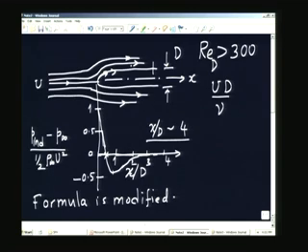If there is friction, there will be some pressure drop due to friction. Therefore, whatever pressure drop I am measuring also contains some amount of pressure drop due to friction effect. But when I am measuring, I do not know which portion is due to friction, which portion is due to the stagnation process. When I am stagnating, the velocity head is going to be added to the static head. Now, because there is a certain amount of friction, the pressure difference consists not only of the dynamic head, but also of some amount of frictional head due to friction loss.